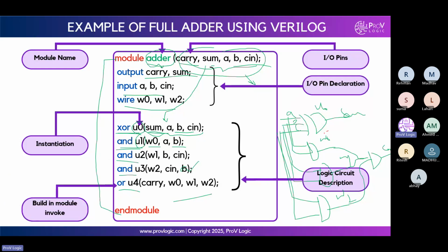So these all are wire connections. That's why we declare it as a wire here. Wire is a data type, and for a combinational logic circuit we use it as a connection because it doesn't store any data. We have two types of data types: one is a wire, one is a reg data type, registered data type. Registered means it stores data. Mostly for sequential logic circuits, to declare the outputs, we use a reg data type. For combinational logic circuits, we use the wire data type.